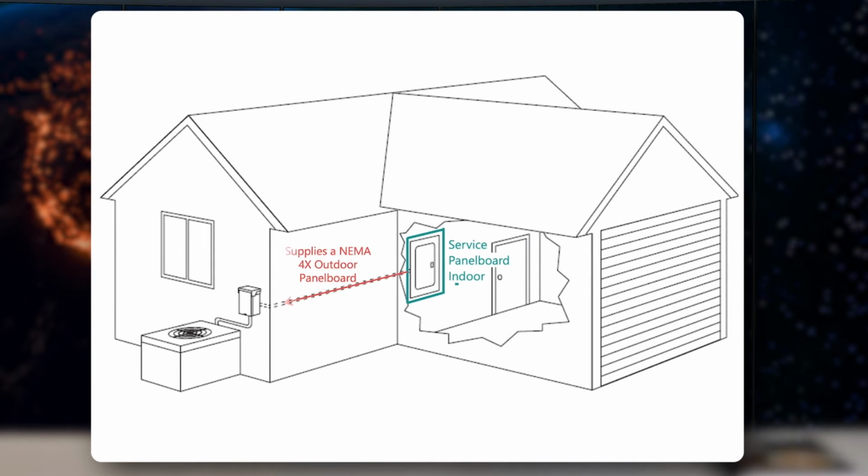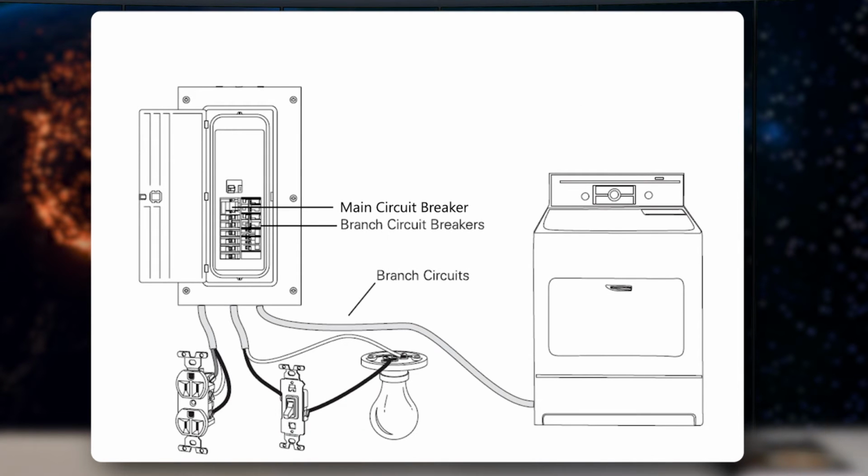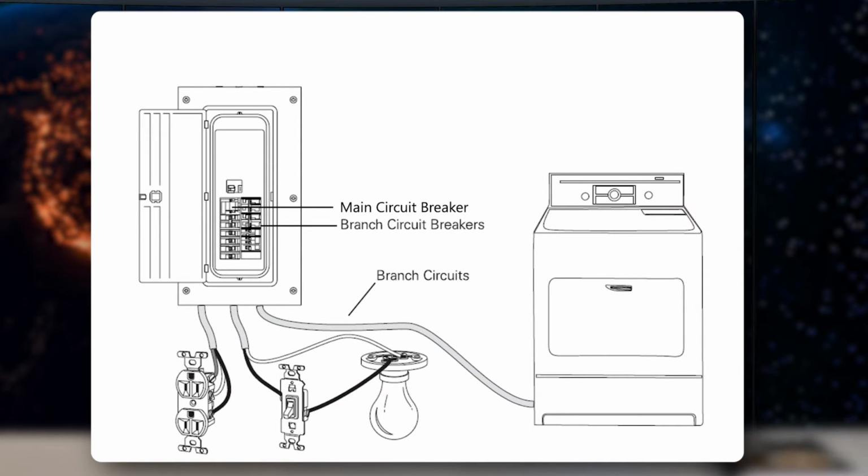There are also panel boards with NEMA outdoor enclosure types like 3R or 4X for outdoor applications, mounted on the outside of the wall. In general applications, panel boards shall comply with UL 67. In most cases, a standard panel board comes with a ready assembled integrated main circuit breaker connected to its internal busbar system. The integrated busbar system splits the power to several branch circuit breakers, which will be field added at the time of installation, flexible to the individual application, to protect all the different loads in the house.